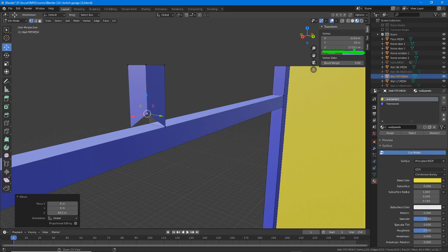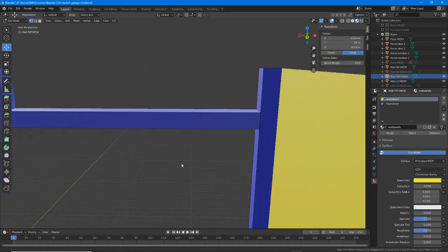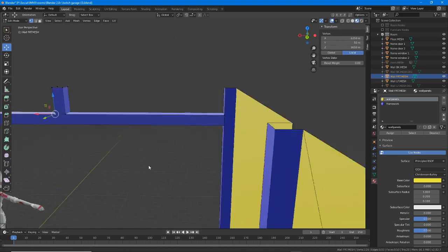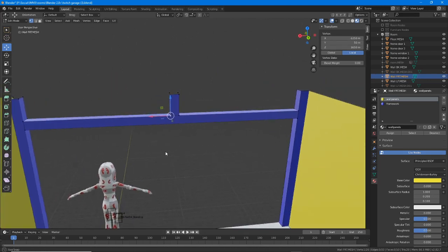Currently it's now at 1719.5. So if we select our vertex again, just to double check, 1650, we select that vertex, click 1650, and it drops it into position precisely where we need it to be. Obviously, if the surface is angled, it's a bit more complicated to do that.